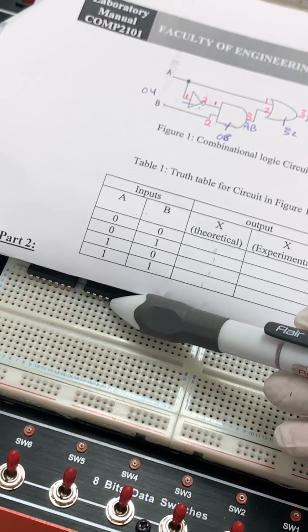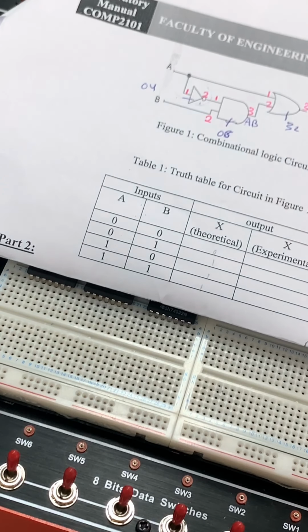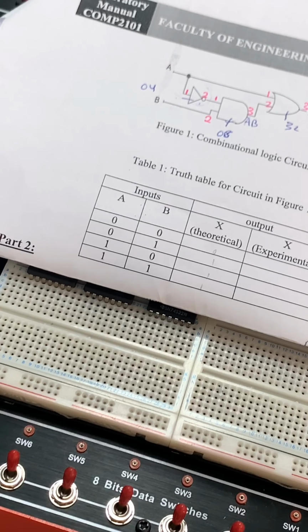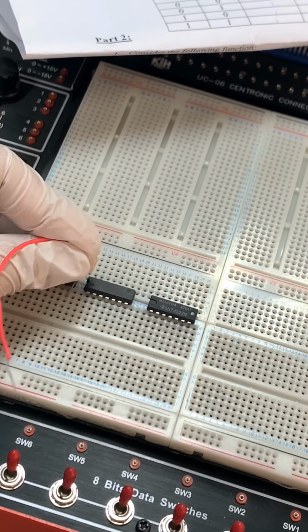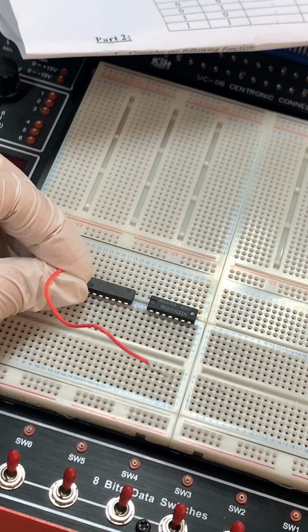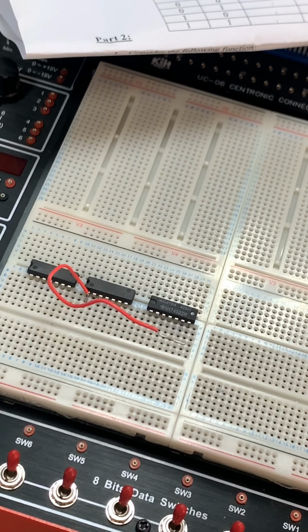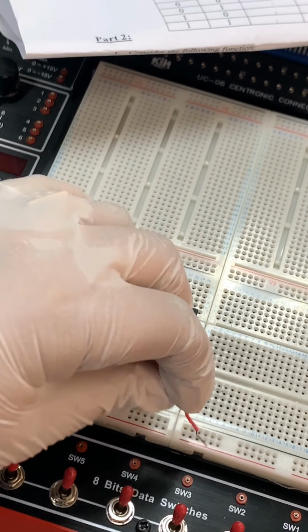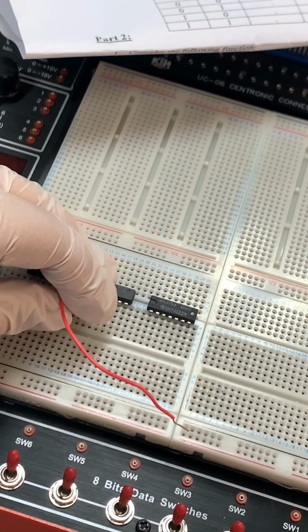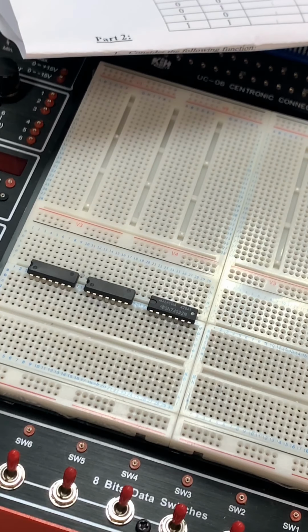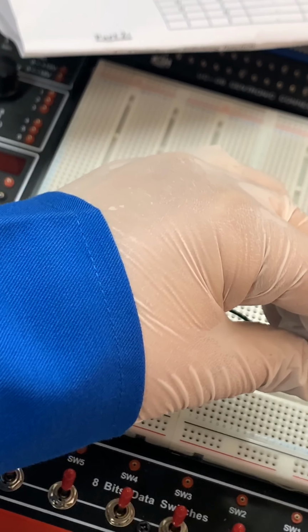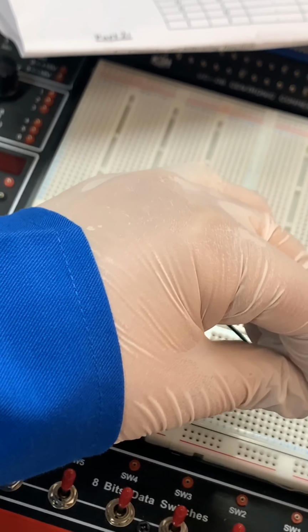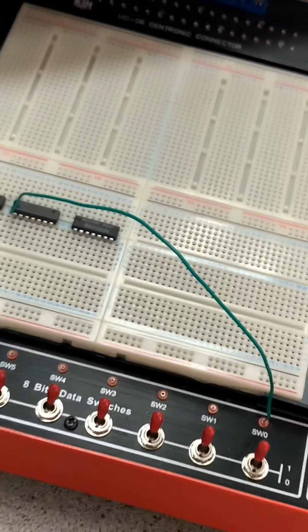Okay. So in this arrangement, I will take from pin number 1 for the inverter, which is the second one. I need pin number 1 for the inverter. So I will take a small wire, pin number 1 for the inverter, which is this one. Where I'm going to connect it for A. So this is, for example, or let's take a long wire so that it reaches. So this is pin number 1 and this is A. Okay. So now I connect A to the switch.